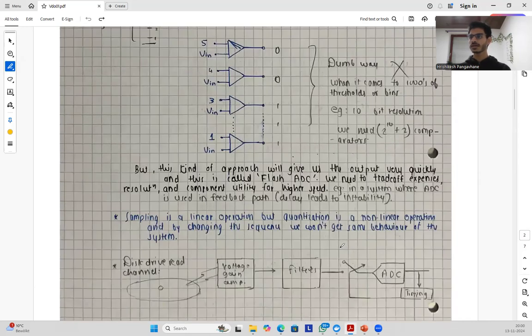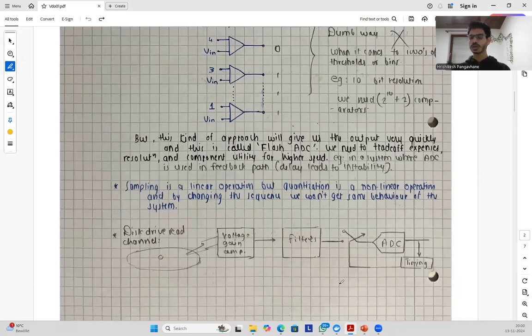So here we need to design a system which will convert the data. The data we will be reading is super analog data, with a very low voltage. It is a very small signal, analog in nature. What we have to do first is amplify that signal. So we will use op amps, or amplifying circuits, which will provide it some voltage gain. When it is amplified with respect to voltage gain, then what we will do is